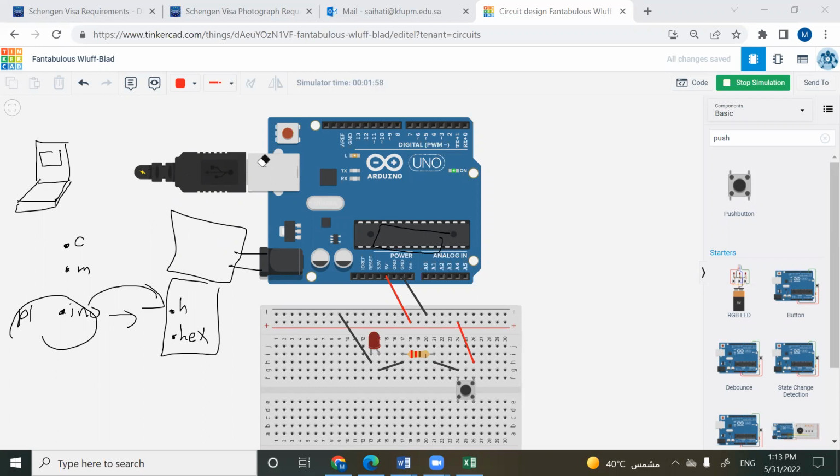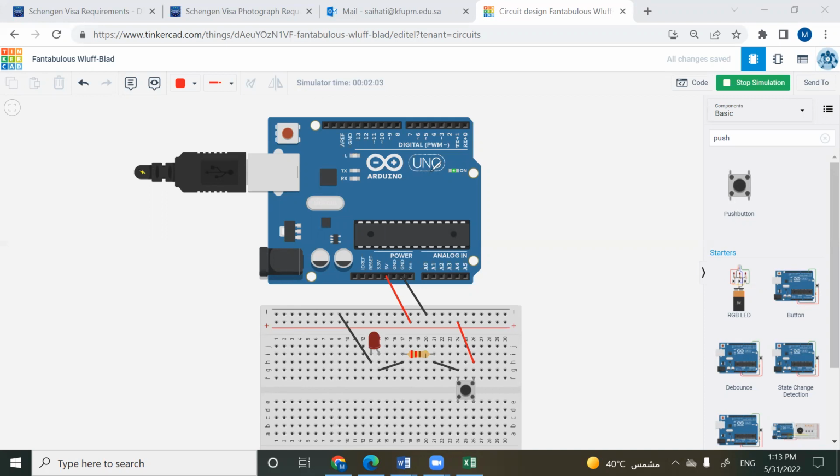Okay, I want you also to notice the other connection. In here, you can see pins 0 and 1. These are two pins, but they can be used as TX and RX, transmission and receiving, and you have another device that you are using as transmit and receive. You'll be using it this way. But try to avoid using 0 and 1 for the time being. I don't want to go into details. Am I clear?